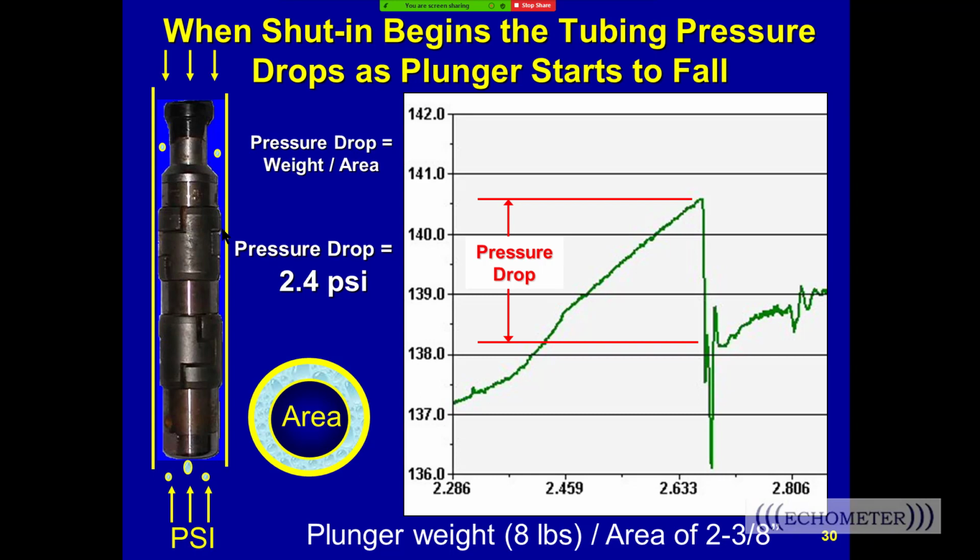But to find holes, you can see holes both by taking a fluid level shot, there's a dual shot method Carrie Ann's going to talk about in the future, and by the plunger going by the hole. But if the hole is in the horizontal section, then the plunger is not vertical anymore, and there's no plunger weight on the gas. So I don't think it will work if it's in the horizontal section of the well.